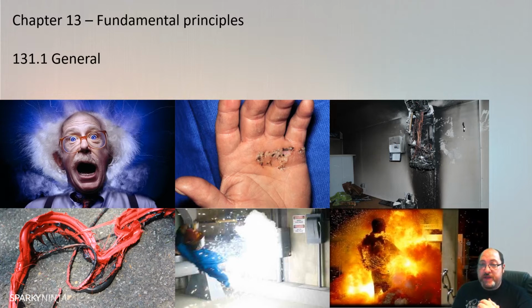livestock or property must not be exposed to any risk from using the electrical system. Okay, and it gives us some examples of what we're looking at. So we have risks from shock current, excessive temperature likely to cause fire, burns, injurious effects, ignition of a potentially explosive atmosphere, undervoltages, power supply interruptions, arcing and burning. So there are a number of scenarios, there are a number of risks that can occur. It's not just electric shock. We've got to think of all these other scenarios that can occur and all the risks to persons, livestock and property from working with an electrical system.